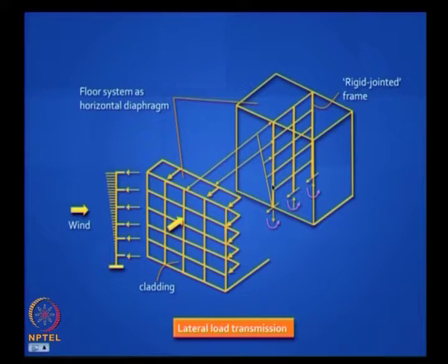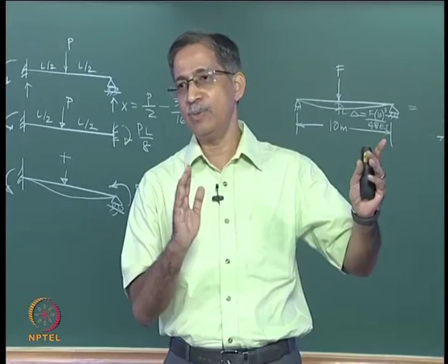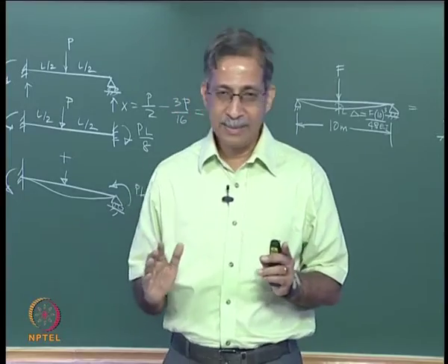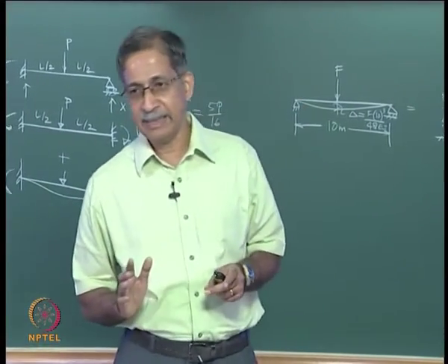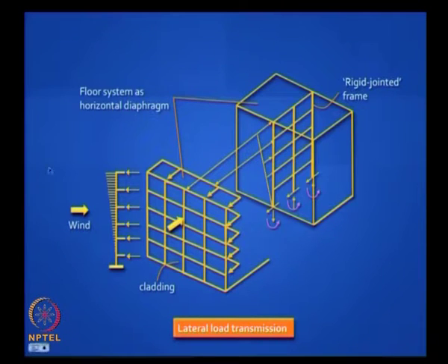How do you do that? Well, some people take just the wind pressure and multiply by the tributary area, that means half the width on one side and half on the other. Well, that is one way of doing it. It works if your frames are all symmetric, but that would mean that your end frame, the last one, would take half the load compared to an intermediate frame. Do you think that is the way it is going to behave? Why not?